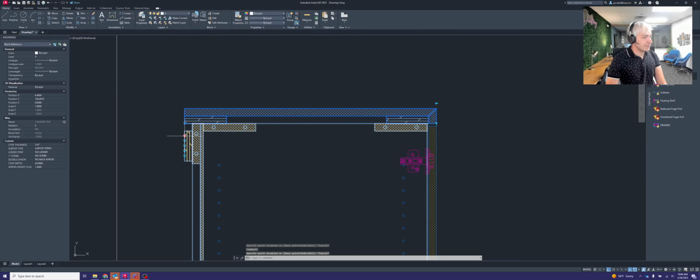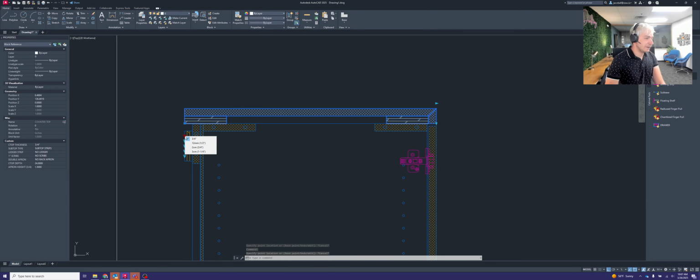Now, on the left-hand side of that block, you can see that there are a number of options here. The first one is countertop thickness, which relates to the material of that countertop. If the countertop is veneer or laminate, it will be 3/4 of an inch. That is standard across the board. If the countertop is solid surface, stone, or quartz, it will be one of these other 3 options below: 12 millimeters, 2 centimeters, or 3 centimeters.